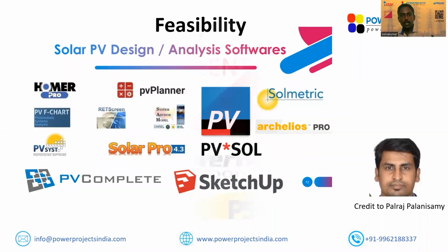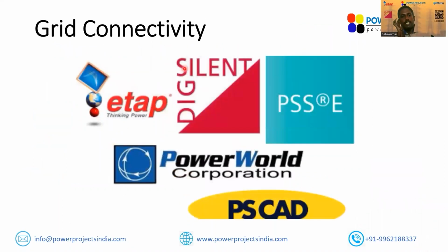Then let's go to the next slide. What about this simulation software? ETAP, DIgSILENT, PSSE, PowerWorld, or PSCAD. I guess the SIMATE someone has talked about will come here exactly. What will these simulation softwares do? These simulation softwares help you to understand the impact of the solar plant on the grid and the impact of the grid on the solar plant in terms of voltage profile, equipment loading, losses, and short circuit current.